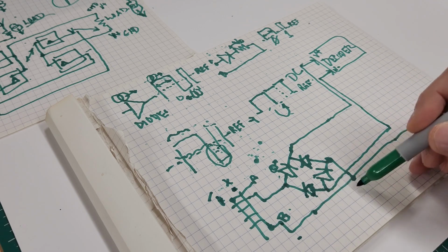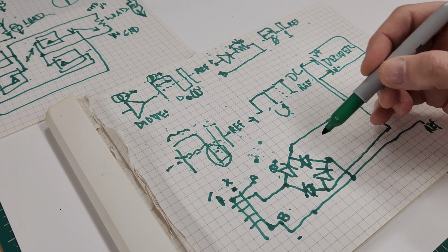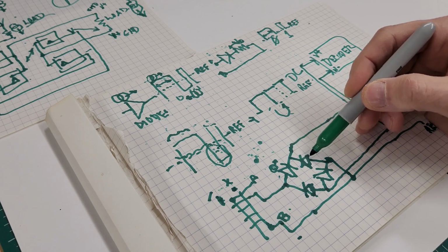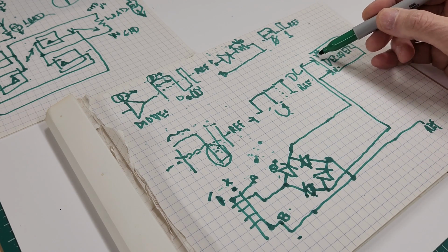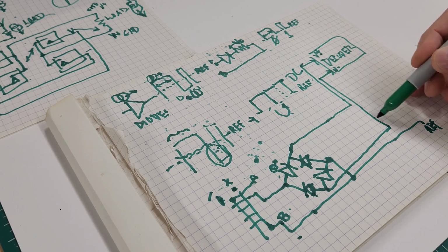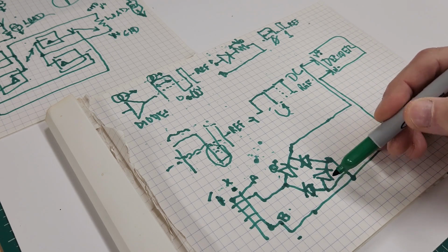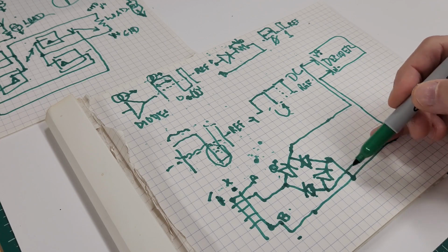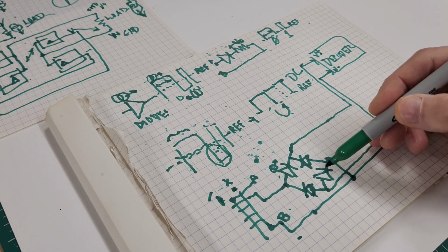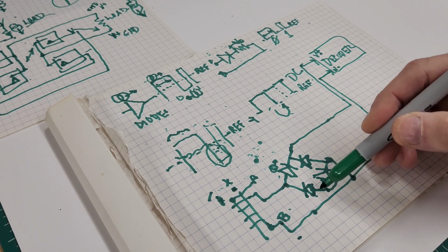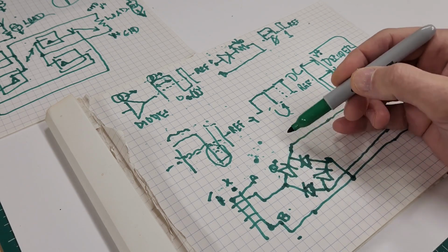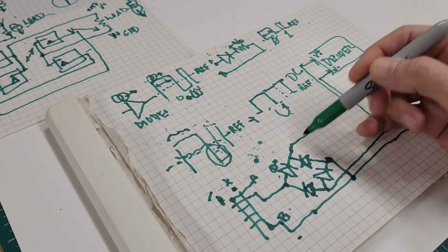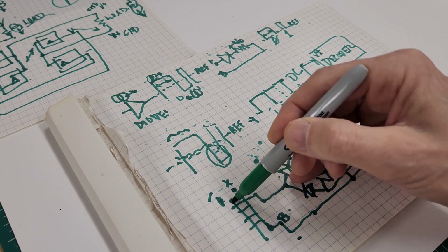We get a push coming this way. Well, it can't go through that diode, so it's got to go through this diode, and up it goes to the plus. And it wants to come back. It's going to return this way. And now we've got a plus here, so it's not going to be enticed to go that way. So it goes through this diode, and it won't go through that one again because there's a plus up here. So it's going to go back to the track here.